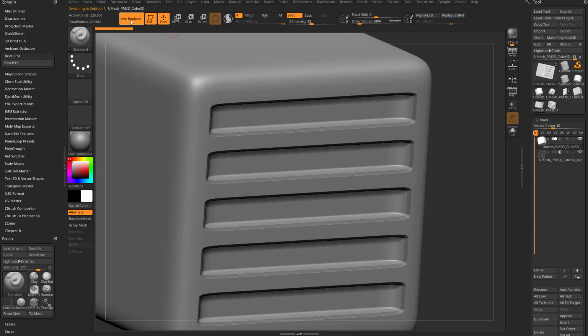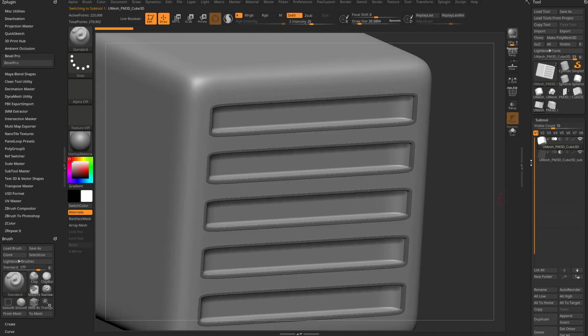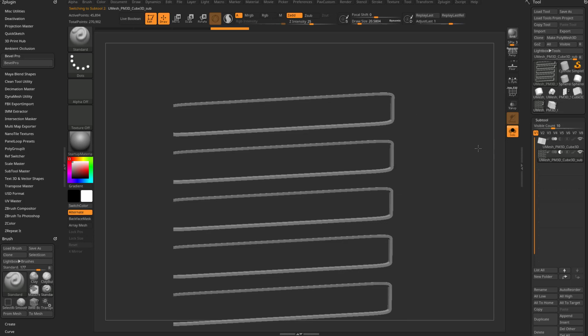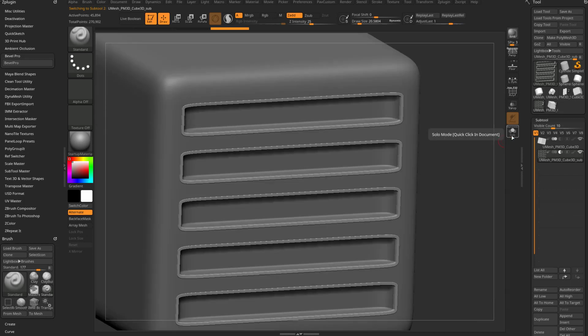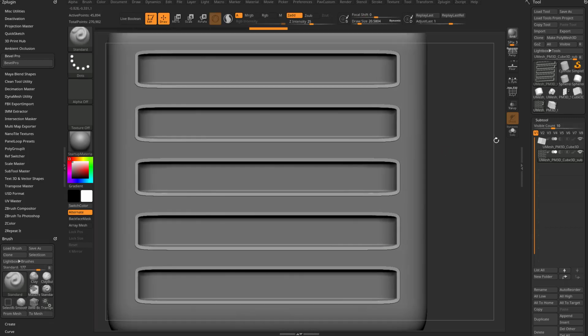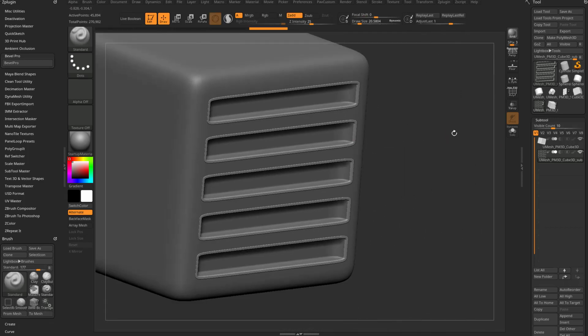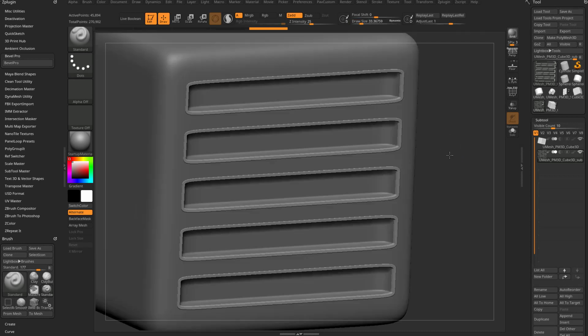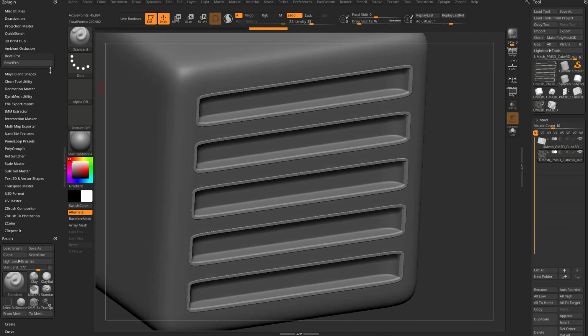And sometimes what I'll do, and I use this on my buffalo, if we just grab this UMesh, this is actually pretty cool geometry. So you can use this geometry if you want to just take that from subtractive to additive. You can use this as kind of like a liner. Pull this out a little bit, maybe inflate it, go through there, and now you have like a rubber gasket around those openings. So you can also use Boolean or Bevel Pro to add interesting geometry.